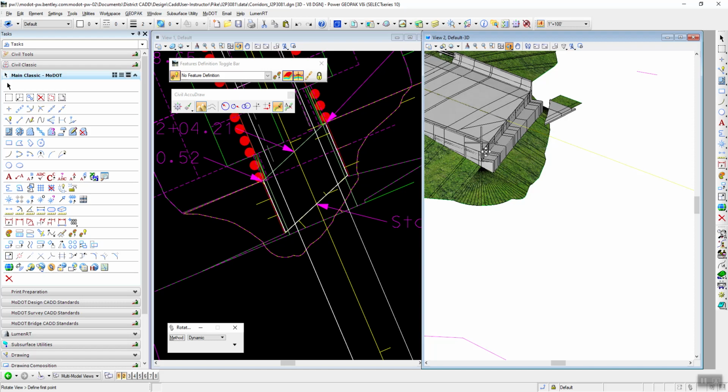And then we're going to add in a bridge template, and that bridge template is going to go into the mainline template, and we're going to create a second clipping corridor, and it's going to clip out that bridge information. Now, the way we do it in the manual, we use clipping corridors, but you could just use a MicroStation shape if you felt that was easier, and a lot of people think it is easier doing that. But we're going to go ahead and show you the clipping corridor method first, and then if you need help with the MicroStation shape method, just give us a call here at CAD and we'll show you how to do that.